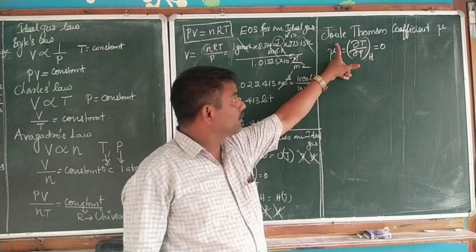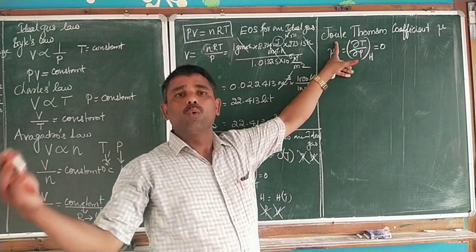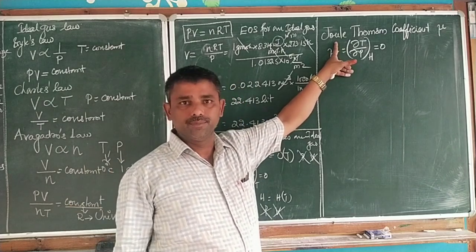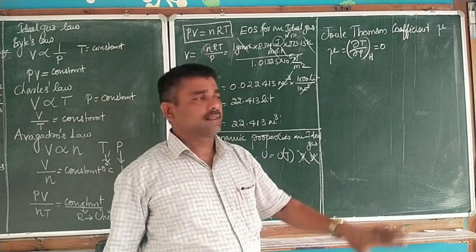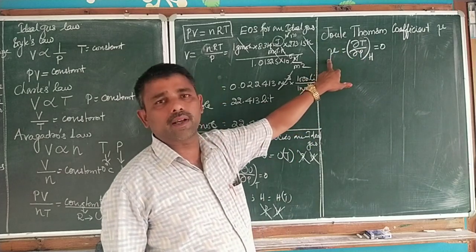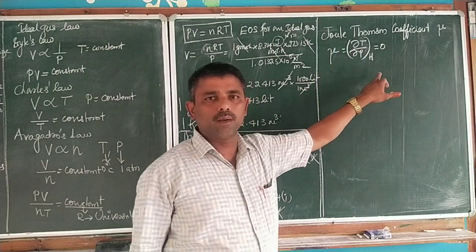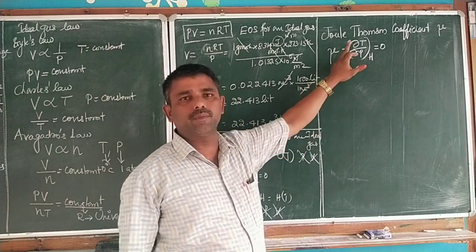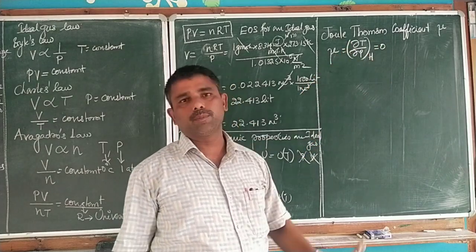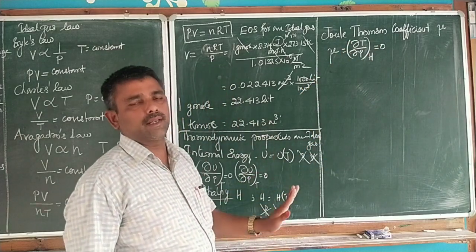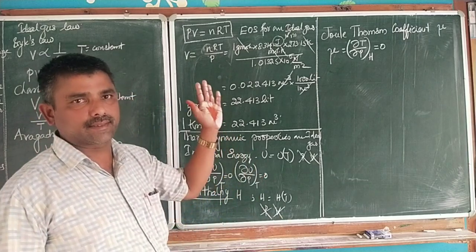This Joule-Thomson effect is the main reason behind the AC unit in our home appliances. Clear? It will be discussed later. The point is the Joule-Thomson coefficient for an ideal gas is 0. It is nothing but the variation of temperature with respect to pressure at constant enthalpy. Clear? These are all the important information for an ideal gas and the ideal gas law.